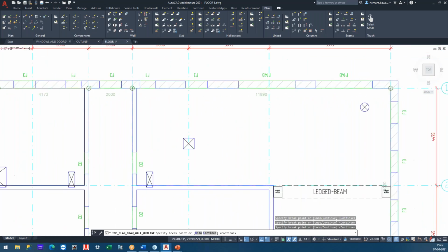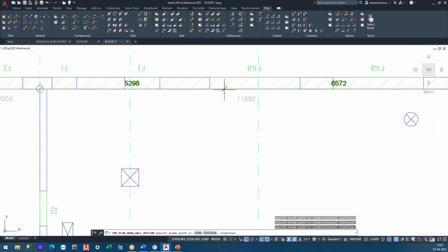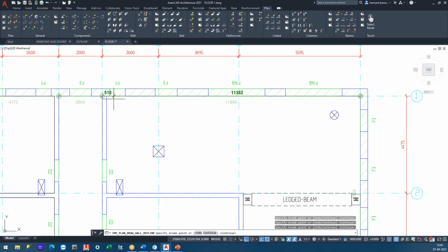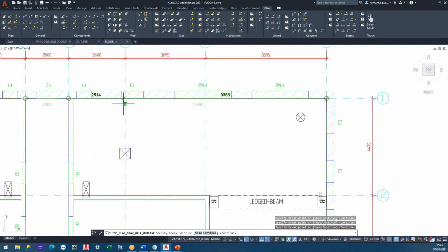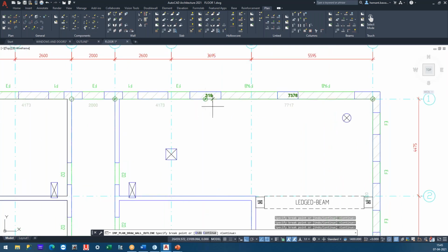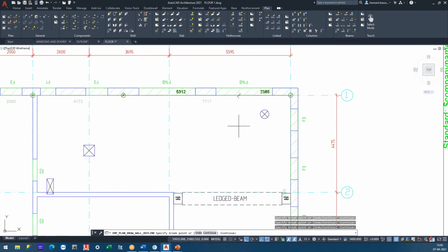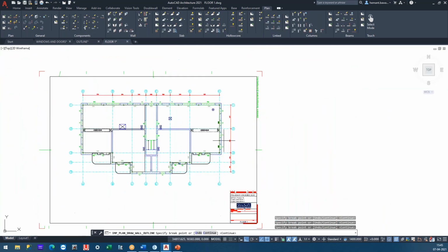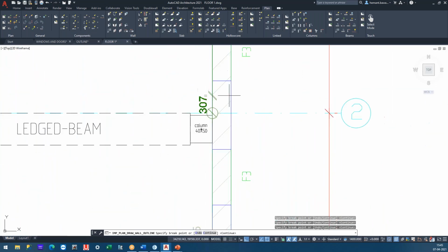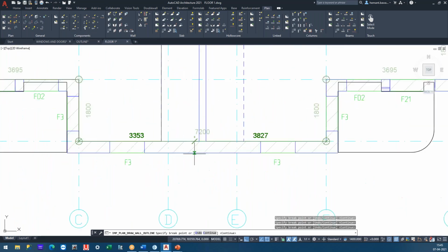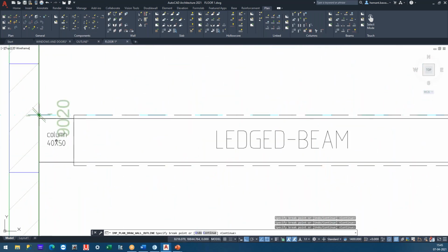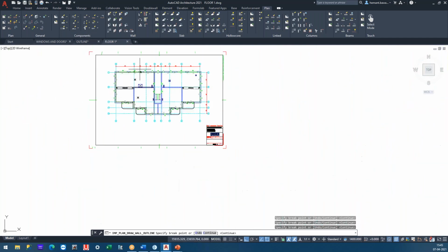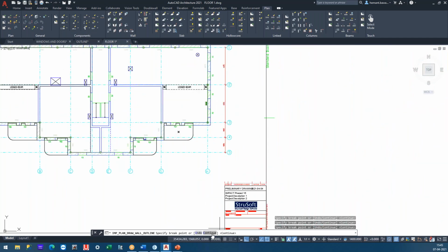As I'm going ahead, as you can see the measurements are given here. So from this point to this point, as you can see this is too long a wall, and we will just split them between, and the split length is given here. I will split all of the walls. Okay, now that the breakpoints are selected, I will just click continue.